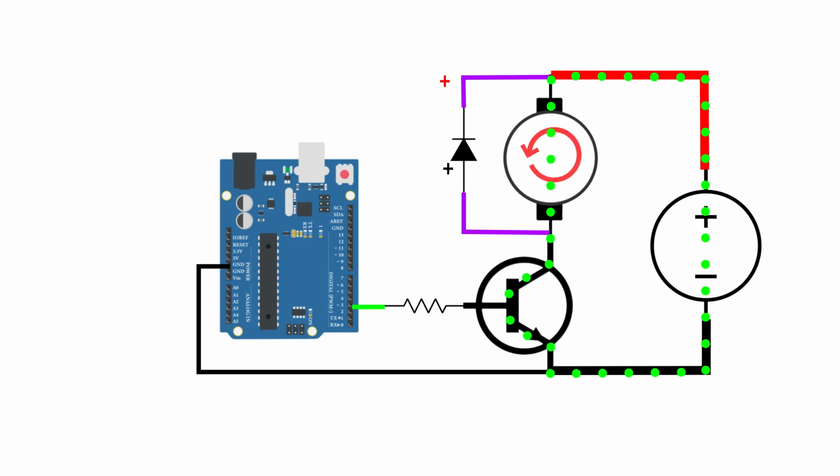However, as soon as the transistor turns off and the motor starts kicking back, a positive voltage is suddenly applied to the diode and turns it on, dissipating the extra energy, controlling that voltage, and protecting your transistor. Great. Now you can turn on and off a motor with a microcontroller.